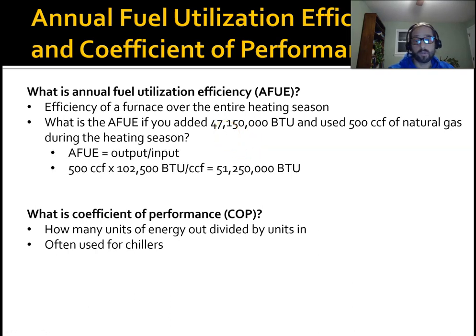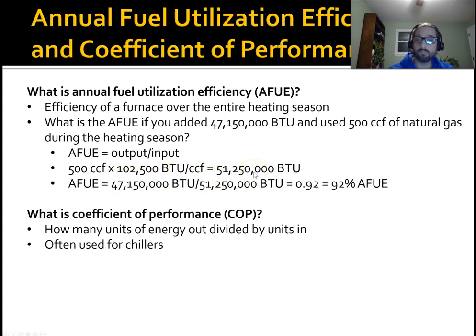That's it. So just make sure that everything's converted to BTUs. So we have CCFs, we convert our CCFs to BTUs, divide, and we end up with 92% AFUE. That's it. So it's just an efficiency, but it's over the course of a season. Excuse me, not at a given time.